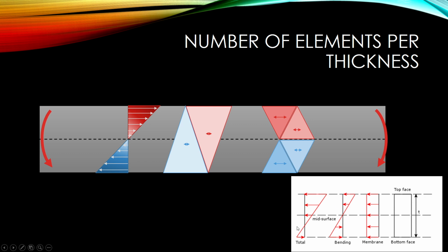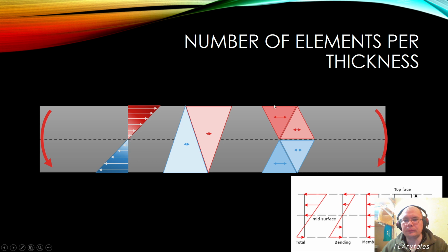So the midplane with 0 stress will go like here. So it means that for this situation, to obtain not only one situation with pure bending, but a more real situation, we need more elements on thickness for describing the stress distribution better, for describing the stiffness better.